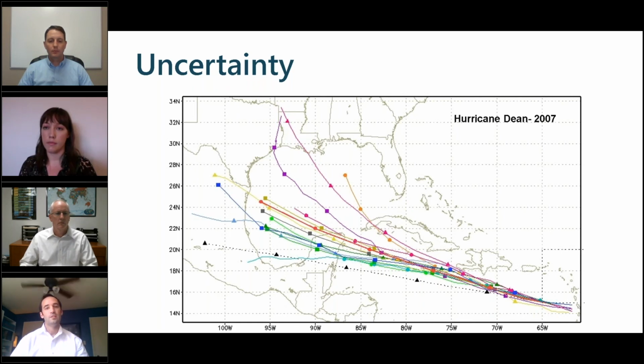So what you can do, in running this ensemble, is select, say, a central tendency model as your single model, that regulatory answer, and you get that single result while you wrap it in the context of the uncertainty quantification that you get from the ensemble. So you get kind of what I would call the best of both worlds. You get the single answer, but you also get it wrapped in the uncertainty associated with it that you can quantify with that ensemble. And again, if you're already using the PEST code, there's not a whole lot different that you have to do.